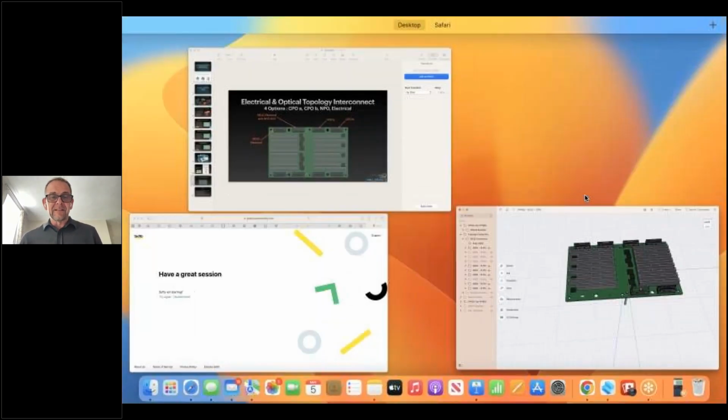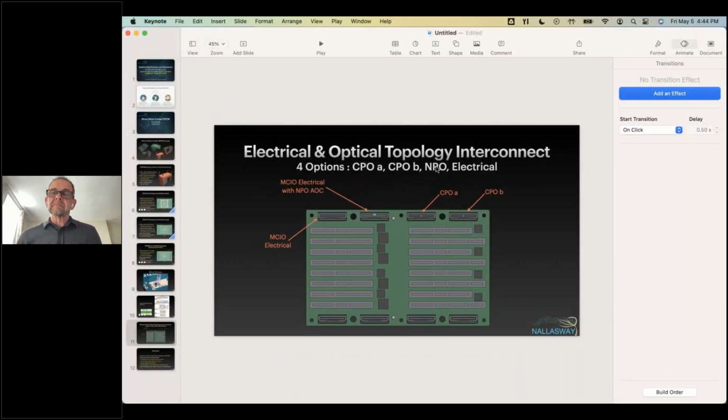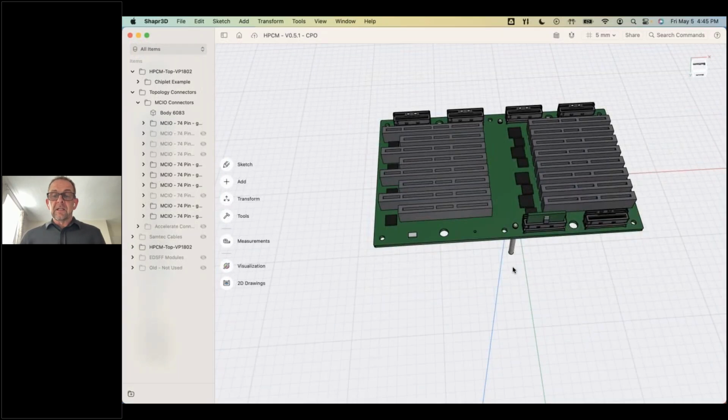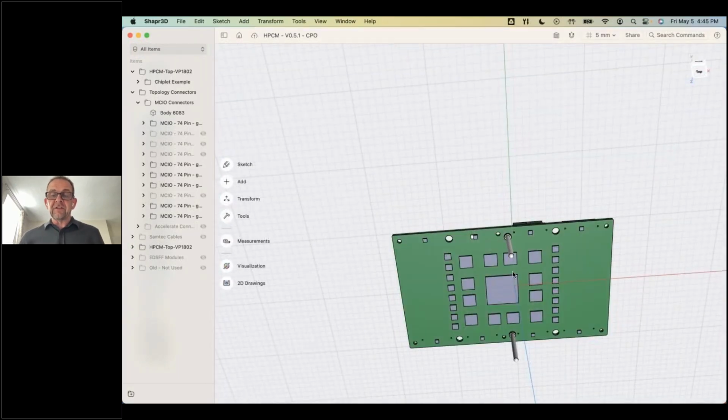Okay. Maybe another question, not about the optics, but just from my understanding, you're talking about these rectangular black connectors. Those would deliver power and data, or power or data, if you stay in the electrical domain, like this MCIO. So the MCIO, but it doesn't. The power to the module comes from these two pins here. These are the 48 volt pins to the module. It's a blind mate. When you plug the module into the wall, it provides 48 volts of power and provides the water, or the coolant, to cool the module.